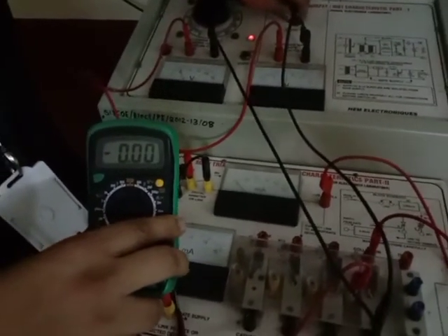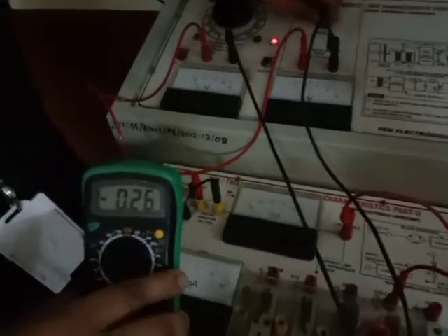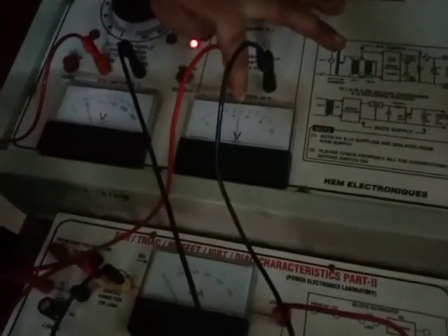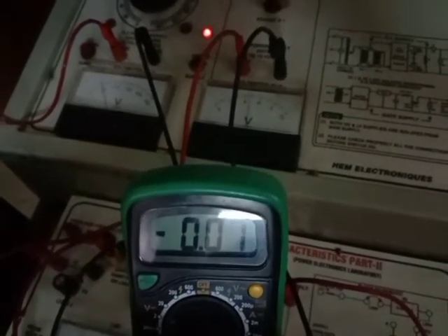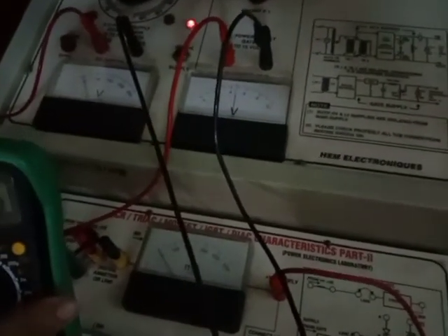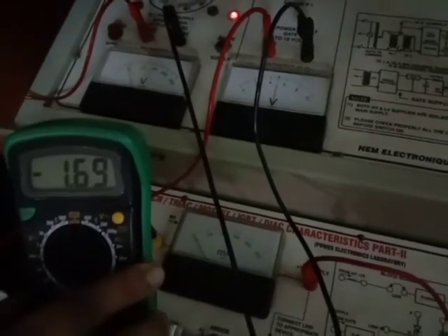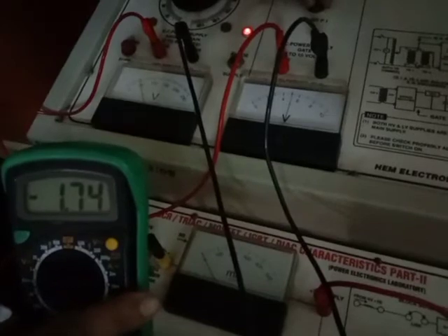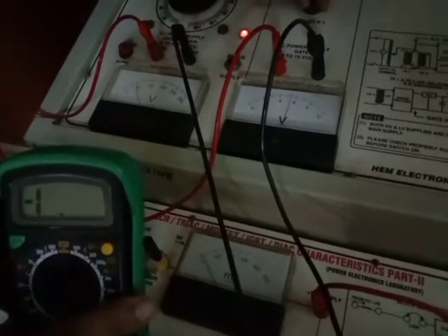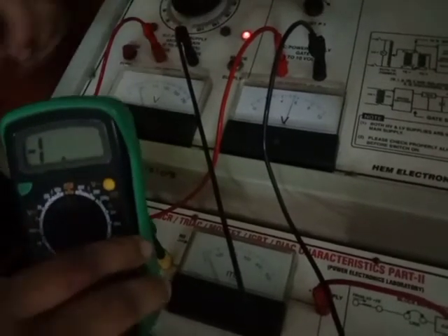At the same time we need to see the current reading as well as the voltage reading. So exactly, you can see here when I am below 5, you can see the reading 0, but as I am increasing, the current is increasing slowly, and suddenly when I am going beyond 5.1, you can see that suddenly the current will increase. So that indicates the IGBT has now started to conduct. And when I increase this value, you'll see an increase in the IC current.